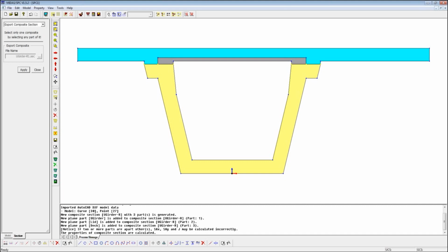Another question that is coming in. So can we use rigid links instead of dummy elements? Rigid links shouldn't be used because they are infinitely stiff, and what they really do is they transfer entire load from one source to another, which is not the true behavior of the deck, because at any given time the force is being transferred with the member whose thickness is this much only.